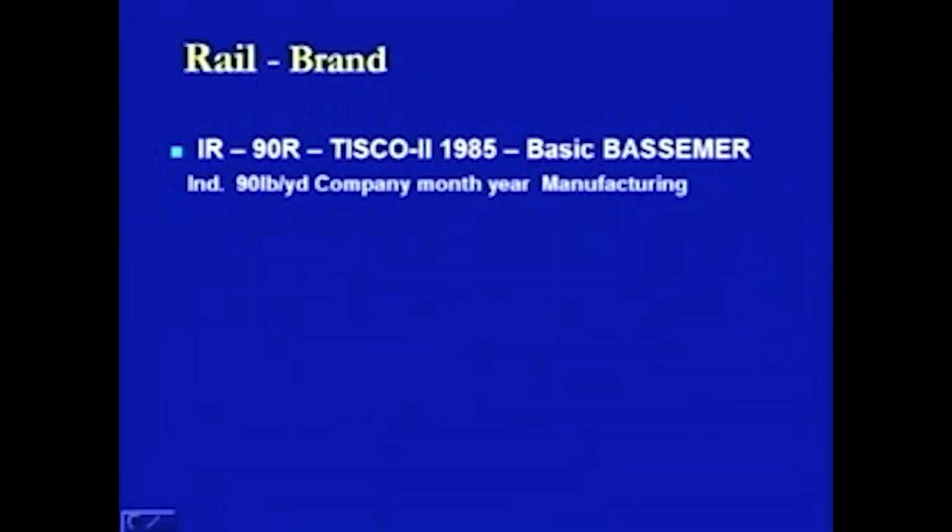Another thing is how we specify any rail. So, what is the brand of that rail? Now, there are different ways of doing it, but the way we use is defined in the form of this line which is being shown here, and this will be engraved on the rail section. It is IR-90R-TISCO-2-1985-basic Bessemer. Now, what does it mean? IR is for Indian Railways, 90R means it is a 90 pound per yard rail section being used here.